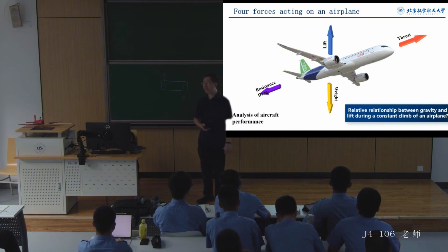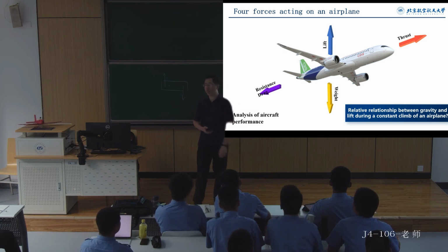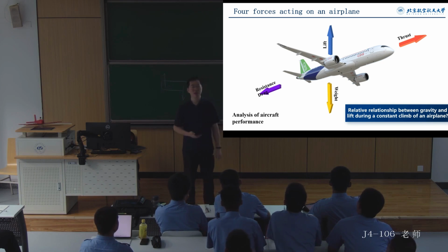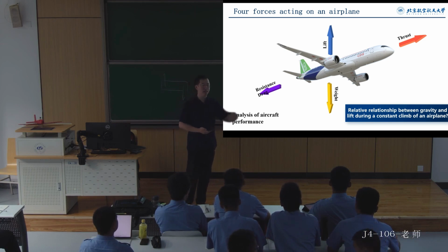I want to ask everyone, during level flight and during climb, when is the lift greater? It's exactly the same, when the airplane is in steady climb and steady level flight.